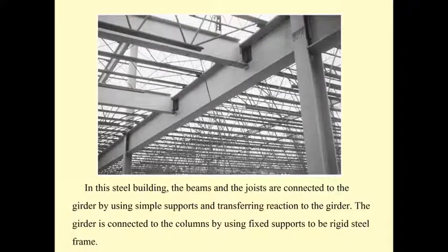And if you consider the connection of the beam and the frame over here, it can be assumed as a rigid joint. However, the connection between the beam and the girder in this figure is not fixed. It is in the form of a pin support. And the joint over here, if it has a slot along its length, can move horizontally. This can be assumed as a roller support.